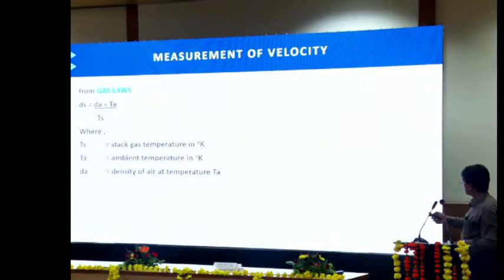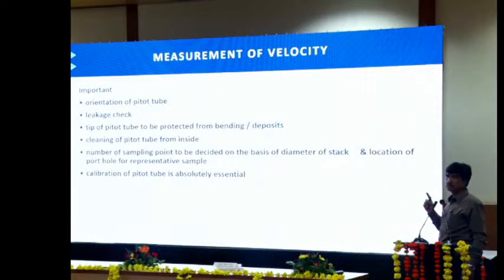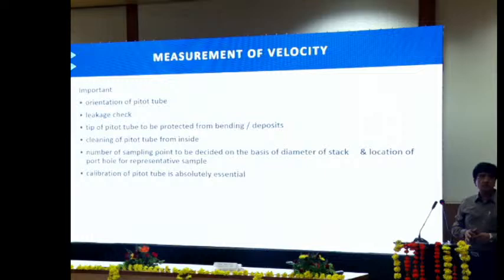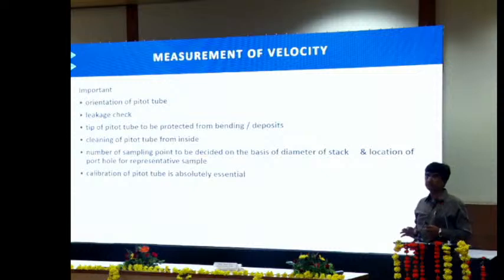Sorry, one point. The calibration of pitot tubes is absolutely essential. No pitot tube is valid till a valid calibration constant is given. Anybody using a pitot tube, do you know how much is the constant which normally they get?